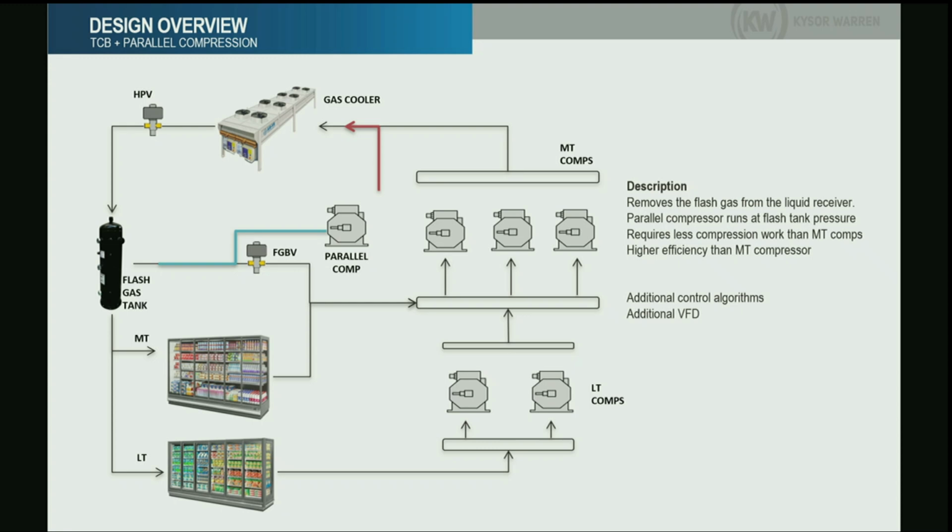And because of that, it will provide some energy benefits for the system as a whole. So just because of a lower compression ratio, that's it? Yes. But it's still doing what this is doing, but just at a higher suction? Exactly. That is one of the things I want to mention, because this doesn't change how much vapor you have, it doesn't change anything besides recirculating in better conditions, right? So this is the parallel compression portion.